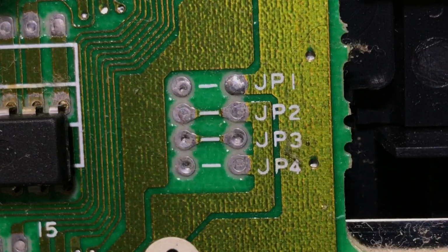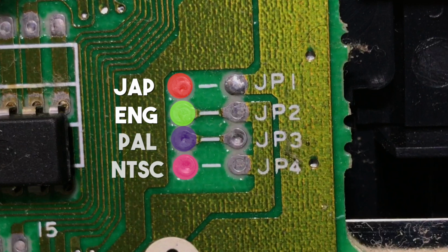If you look at the Mega Drive circuit board, you should see a collection of 8 pads in rows labelled JP1, JP2, JP3 and JP4. Depending on your motherboard, these JP pads might be in a different order entirely. Each of these JP pads are jumpers that set the region and video display settings of your system. The left hand pads for JP1 and JP2 set the language between Japanese and English respectively, while the left hand pads for JP3 and JP4 configure the system to output 50Hz PAL and 60Hz NTSC respectively.